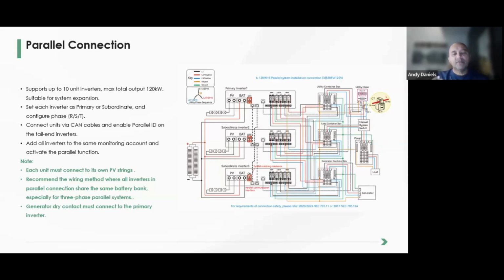Remember that we have to match the voltage sine wave. They have to overlap each other perfectly, as well as obviously the frequency. And the load sharing has to be done correctly as well. So it's very important that when you set up multiple inverters in parallel, you assign it correctly.